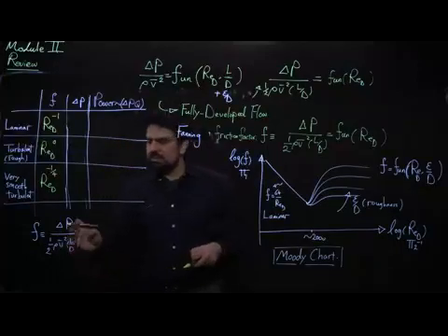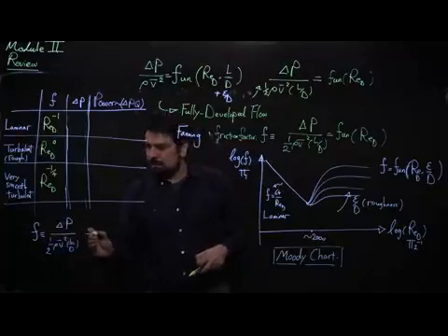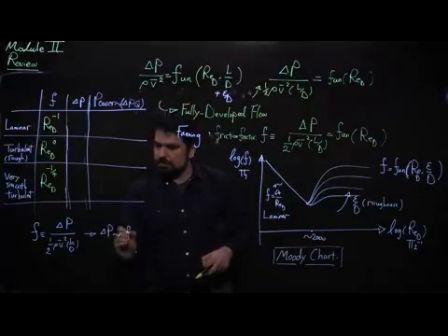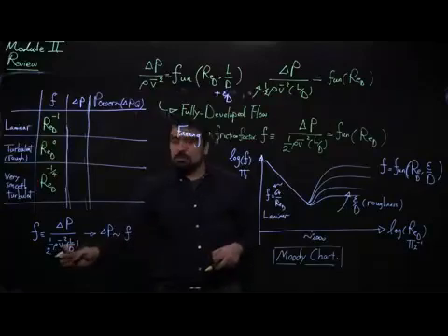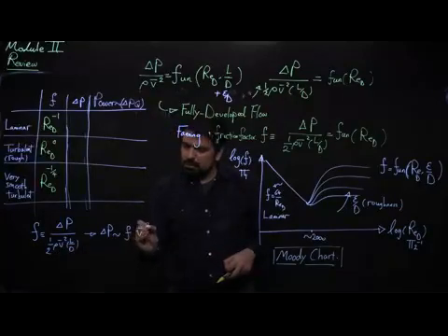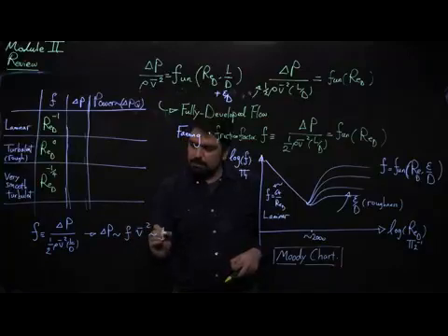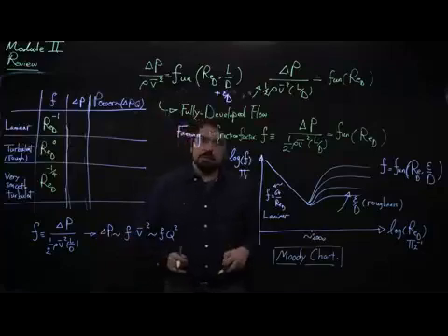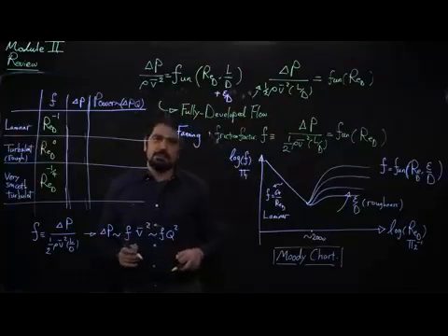But to really get delta P from the friction factor, you see that delta P becomes proportional to the friction factor multiplied by the parameter that you are actually changing. So V average squared comes here. So the friction factor times Q squared will finally form the dependence of delta P.